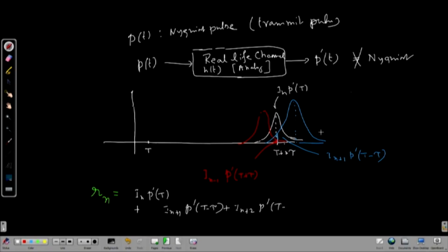So the value of that pulse will be its value 2 tau to the left of the center, times this, and so on. Theoretically it goes up to all the pulses to the right up to infinity. But in practice these pulses are time bound, so you do not have to go too far. After some time the pulses situated to the right will no longer contribute here; they will disappear.